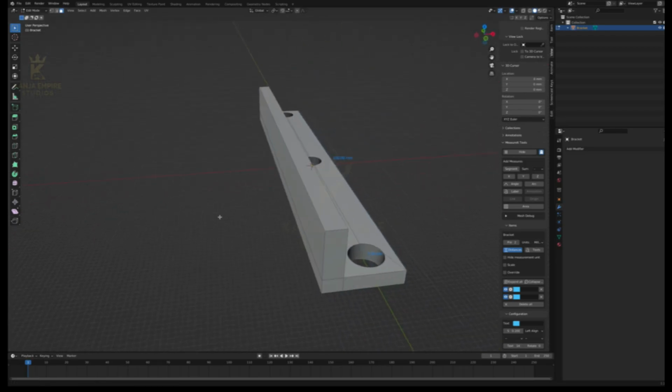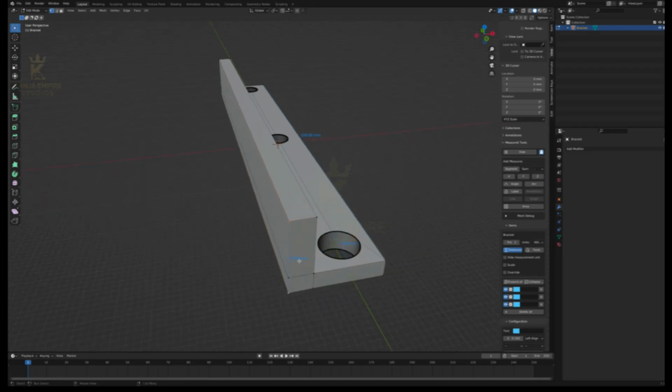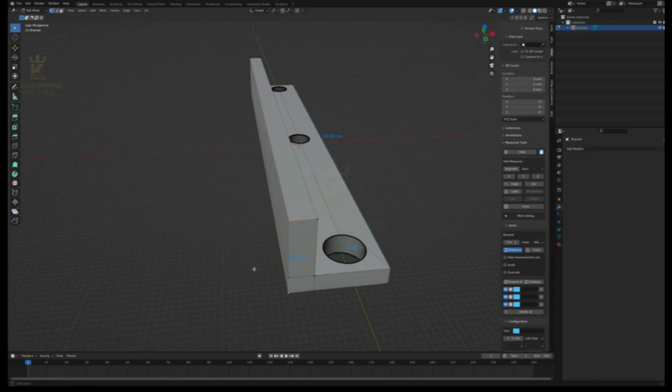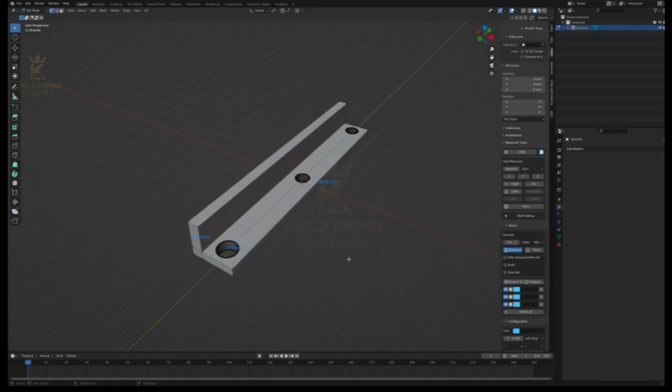And if you want to confirm the distance of everything, let's add a measurement. So we'll go back into the vertex selection mode. We can select this vertex, and let's select this one here, holding shift to select two of them. And let's go ahead and add another segment. Now you can see it's 13 millimeters because we have 3 millimeters plus the 10 millimeters that we added. And now we have a very nice looking bracket, and it wasn't too bad to design at all.